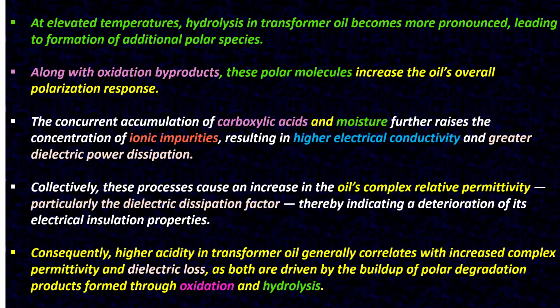The concurrent accumulation of carboxylic acids and moisture further raises the concentration of ionic impurities, resulting in higher electrical conductivity and greater dielectric power dissipation.